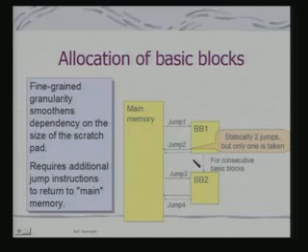Otherwise, the basic framework is that your main code is in the main memory, you introduce jump instructions, migrate part of the code to your SPM, and again put a jump instruction at the end of the code to go back to the main memory. In a way, you are violating the principles of structured programming, but you are violating them to exploit the memory characteristics, in fact, the scratch pad memory energy behavior.